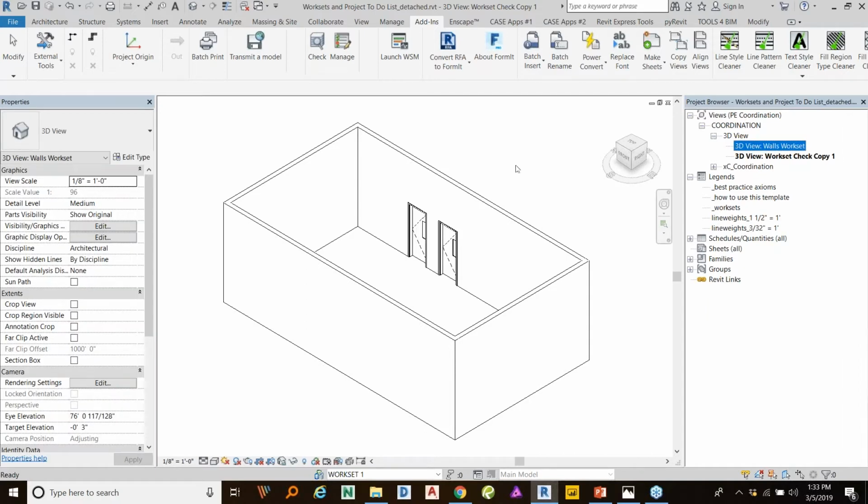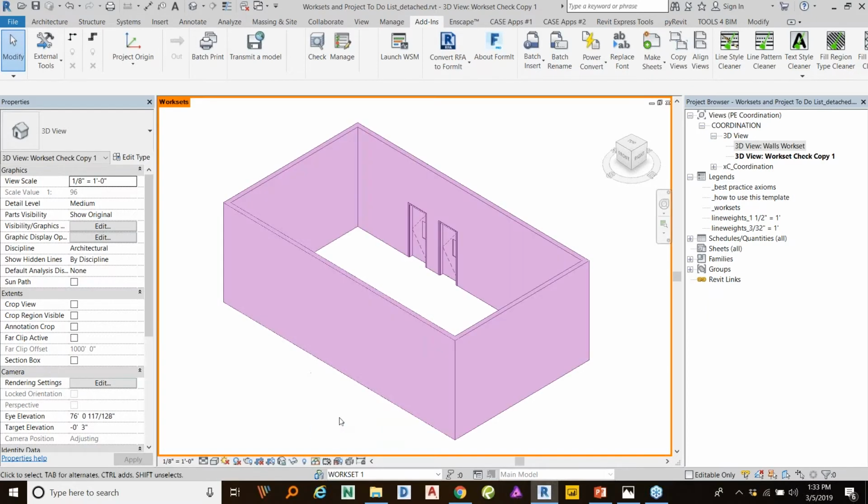And you name the work sets accordingly, and then here you just turn on your work sharing monitor on by clicking work sets, and it starts to color code your model. And so this is a way of having a nice little browser organization that you filter out and will help you coordinate how you're looking at that,